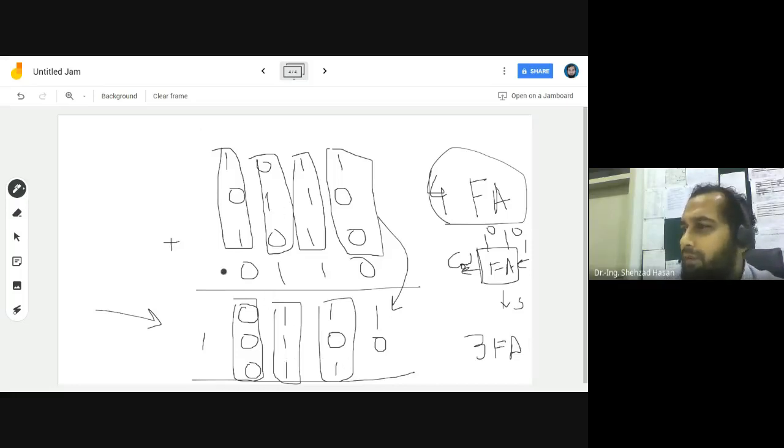Okay, I don't want to go to the next page. I'll try to do it over here. So 10 is simply copied. You're not using anything over here. 101 is going to give a 0 over here at this level and 1 over here at the next level. And then since there is no input coming from this side, this input is blank over here. 111 is going to give a 1 over here and a 1 to the next level. 000 is going to give 0 over here and a 0 to the next level, and then there was a 1 over here.